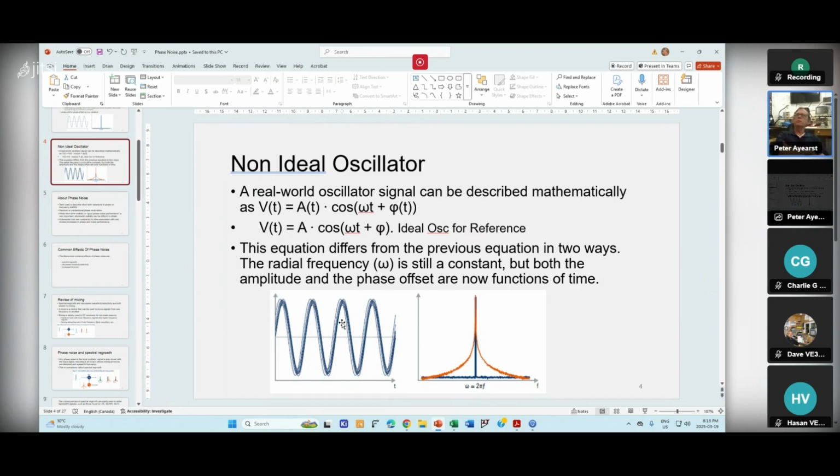Thanks. If I can comment, it's Michael. The picture on the left of this diagram, with the sine wave variation, you see that all the time on an oscilloscope. When the signal you're trying to measure is too low for the scope to resolve it properly, you see this kind of stuff going on. The signal waves back and forth, jitter, exactly like that. I've seen that anyway. Yeah, but if you've got a scope that has automatic setup, it should compensate for that. Oh yeah, you can get around it, but if you're actually looking live, rather than getting it to do the auto set, it moves around.